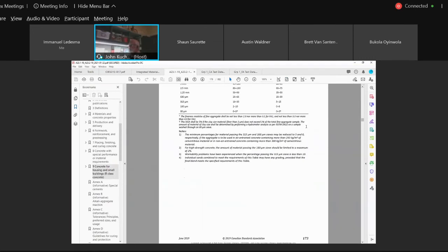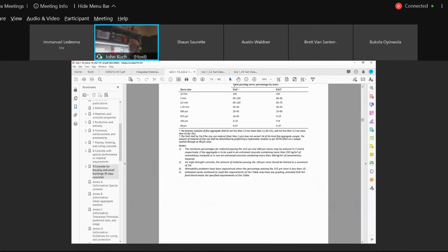You can see it, okay. So we're going to use FA1, and on our spreadsheet, I already had placed those down. Read the footnotes, okay? They talk about the FM here. Remember I said 2.3 to 3.1? Also, there's a little cross here to signify a footnote. These can increase up to 5% minus 200, provided that if you did a hydrometer analysis on it, the minus 200 only had less than 1% clay. Okay, remember, we know that these are silt and clays. Minus 200 can be silt and clays.